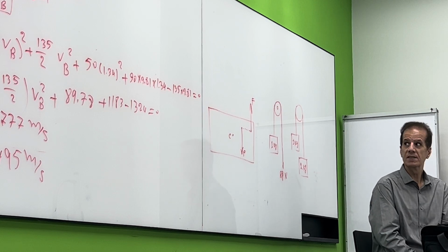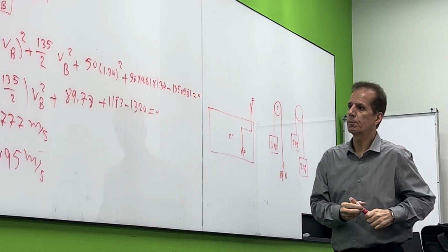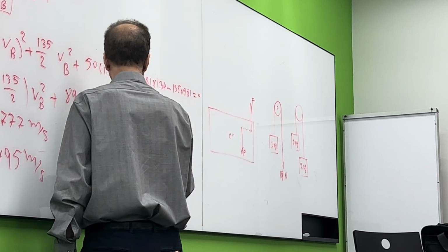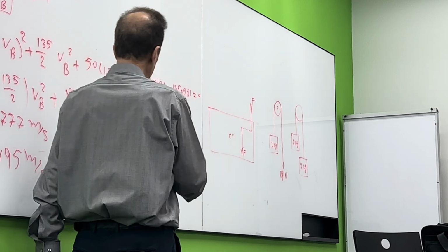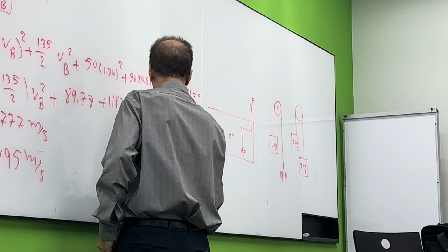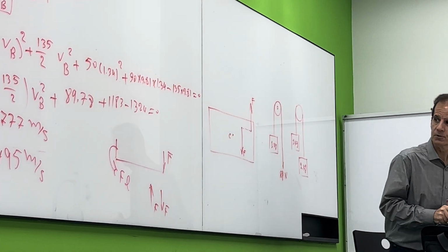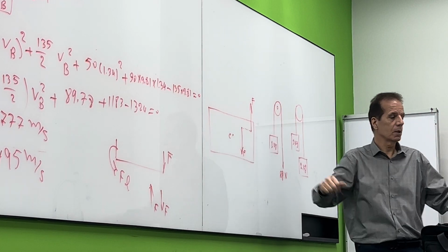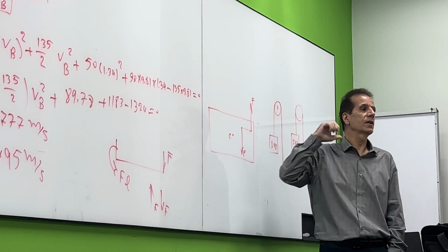The concept is the difference between couple and moment. You know what is moment. When you apply a force, for example here, then you say here I have a moment equals F times d, right? A couple is forces opposite to each other. So there is no resultant force. The only thing we have is a moment, a couple. Where is this board turning about?